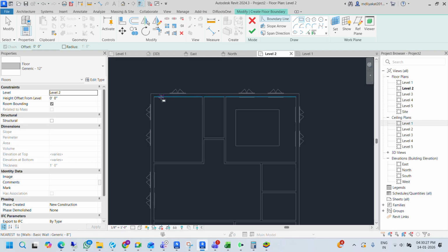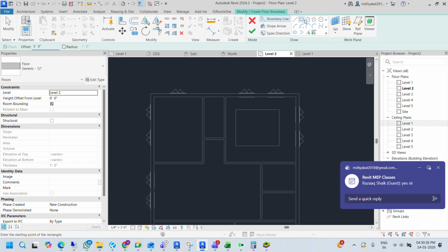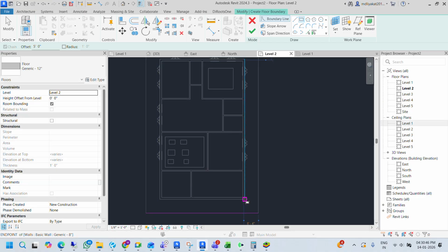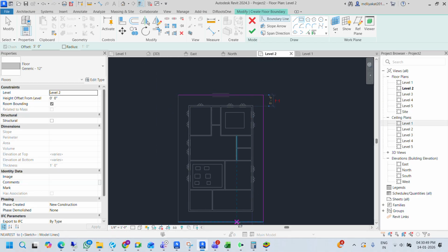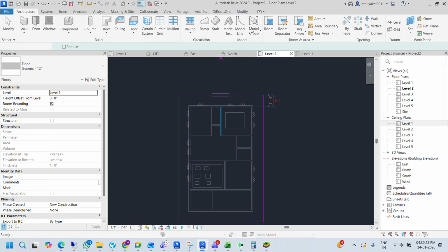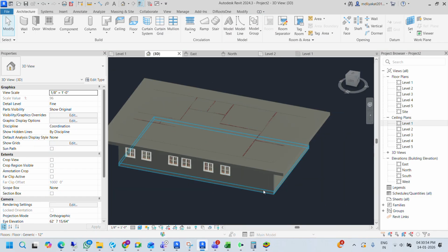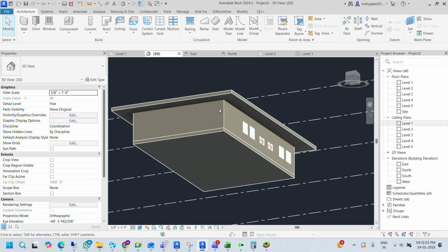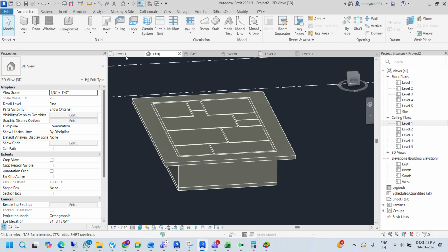I'm making one floor again there. One more thing, while making a floor, we can click on offset as well. I'm making a 5 feet offset and using the rectangle draw, and I'm picking end-to-end points over there. So you will see the offset automatically came outside. So how it will look like this: additional 5 feet from my center wall. Why I chose this, I'll come to in the next part.